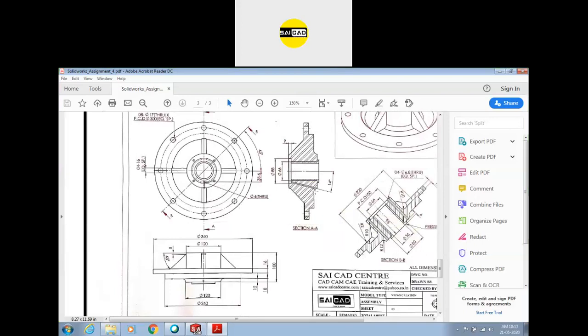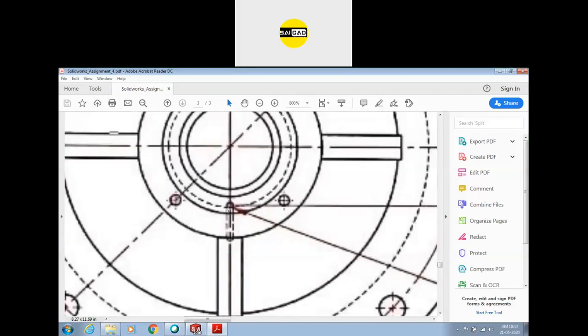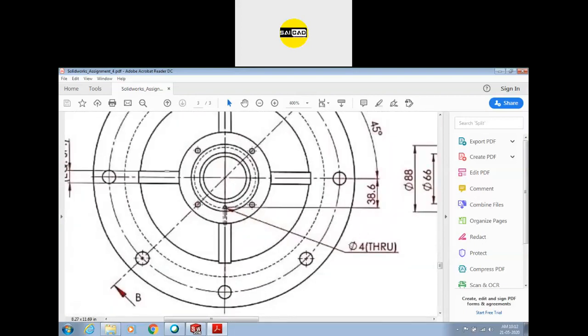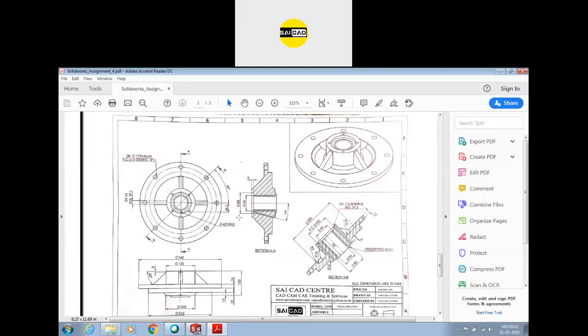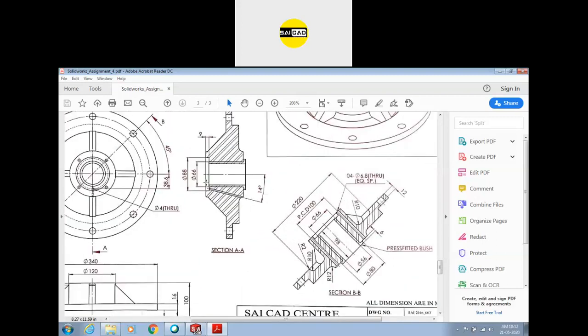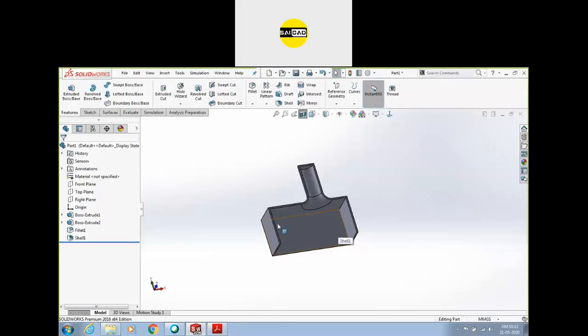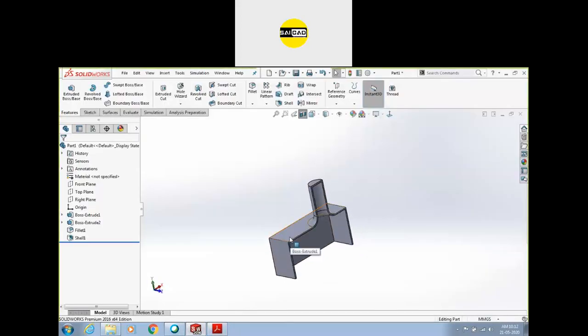So to create this one, you can just create a circle at this point of radius 2 or dia 4, and you can specify a line for the path or for the direction. I have shown you how you can apply the extrude direction vector. The direction vector command I have shown you.